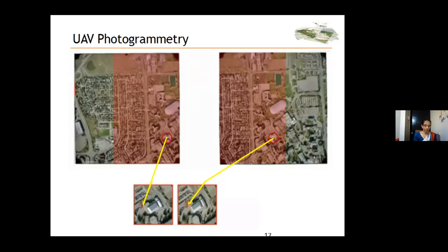If you can see the same objects in the two camera stations or two photographs, these two are the same point within the overlapping area of these two photographs. Then we can use a mathematical model to do the 3D reconstruction based on the photogrammetric principle. This is basically what we are trying to do in photogrammetry for 3D mapping.